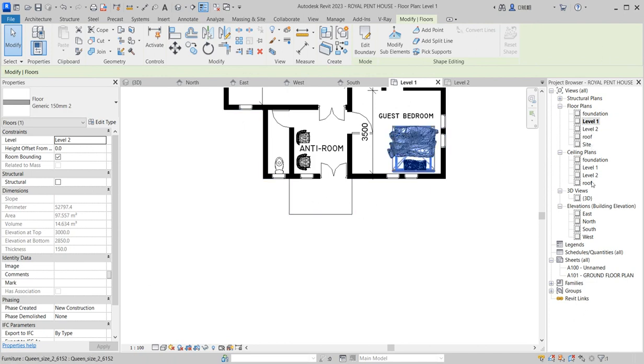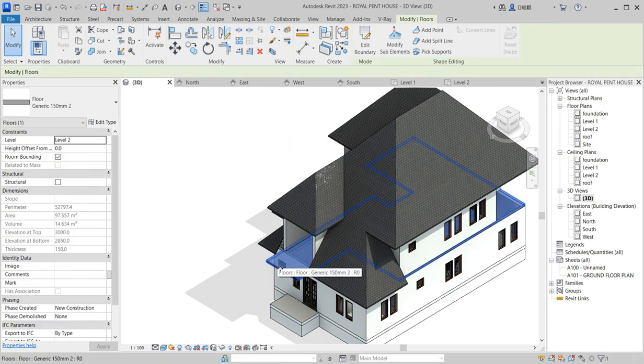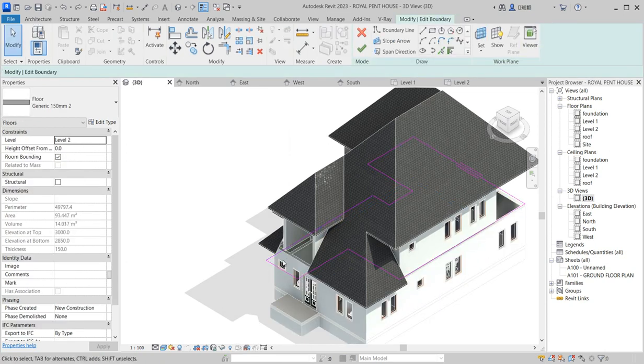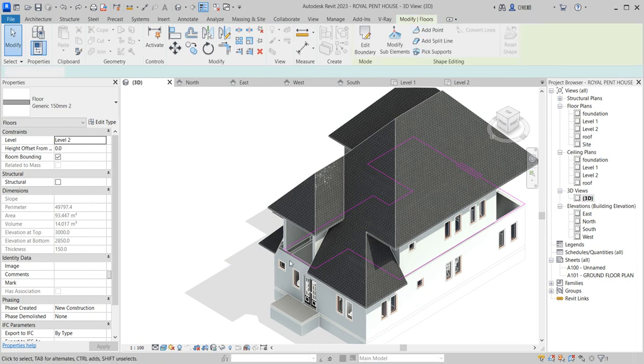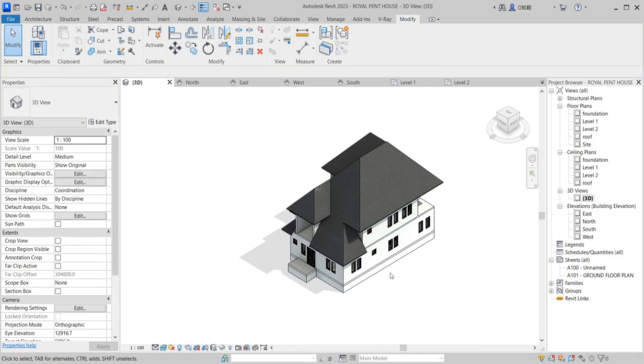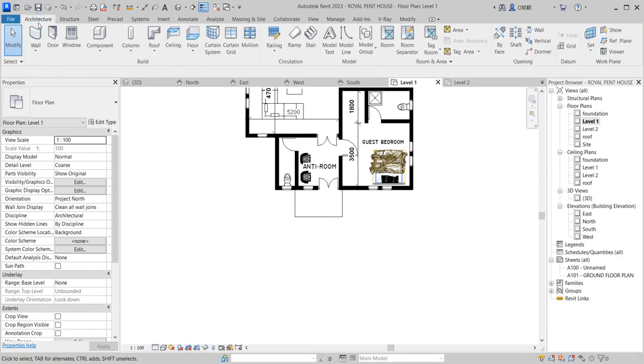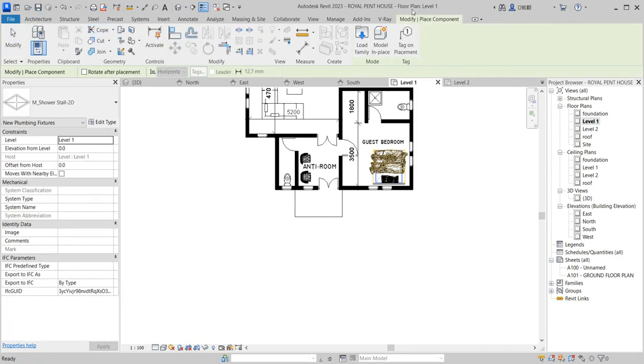No, sorry, it's still staying within that space. Control setback. So it doesn't have anything to come on the outside. So what you need to do there is that we create a standing column from down to the top. So that one we are going to adjust later. That is going to affect this roof as well. So let us quickly create that one, so that we have no iota of doubt of what we are doing. So temporary columns are going to be created.